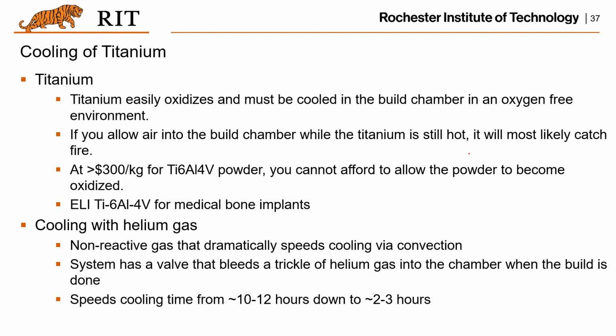The cooling of titanium is very dangerous because it easily oxidizes, and there could be an explosion or a fire if you do not cool it carefully. So first of all, you would like to either cool it in the vacuum or cool it in helium. If you cool the titanium with helium gas, it will speed up the cooling from 10 to 12 hours down to only 2 to 3 hours. Definitely you want a much faster cooling.